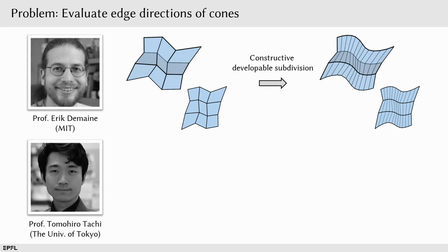And those cones would then be tangent continuous along those strips that would correspond to finer developable strips, PQ strips, while in the other direction they would be joined by globally developable vertices. So the construction would take this coarse mesh and then turn it into a finer mesh that would still be globally developable just by linearly evaluating each vertex or each ruling at a time.